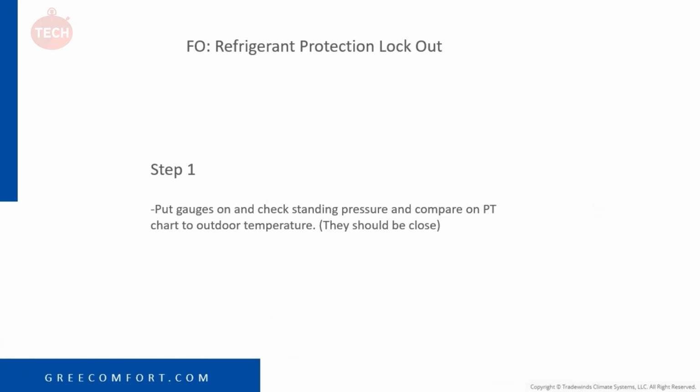So that's why step 1 here, put gauges on, check standing pressure, and you want to compare that to your PT chart. They should be somewhere close.